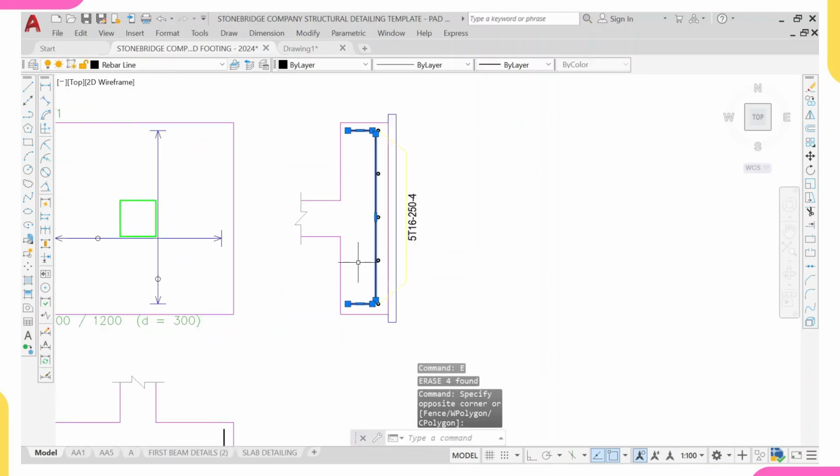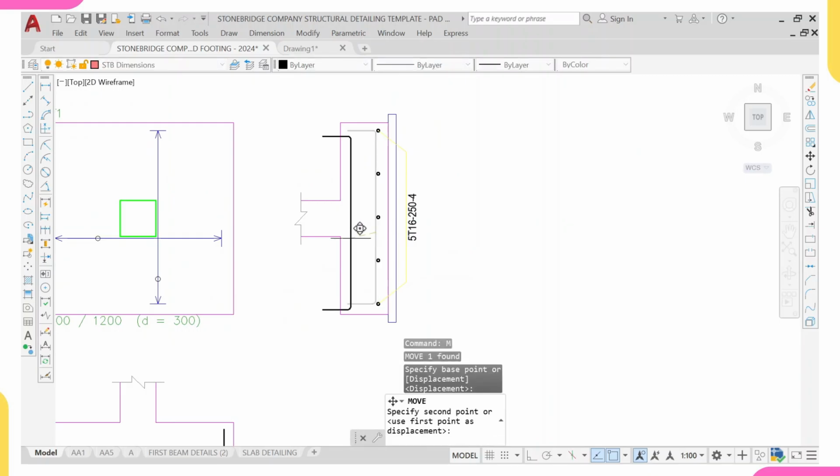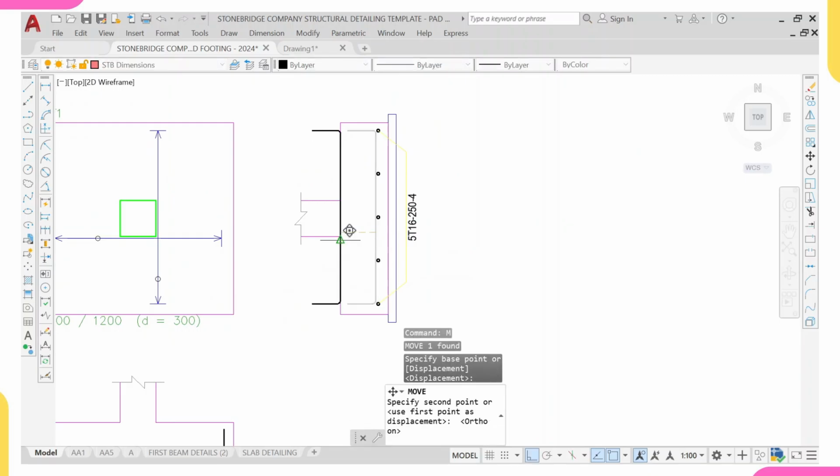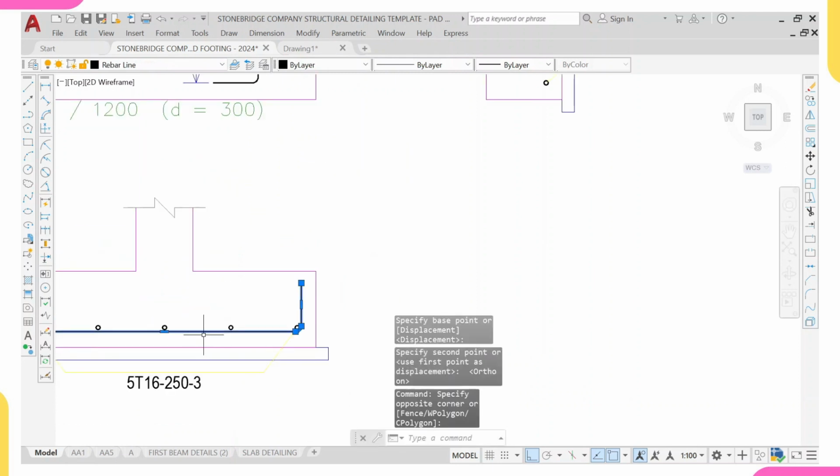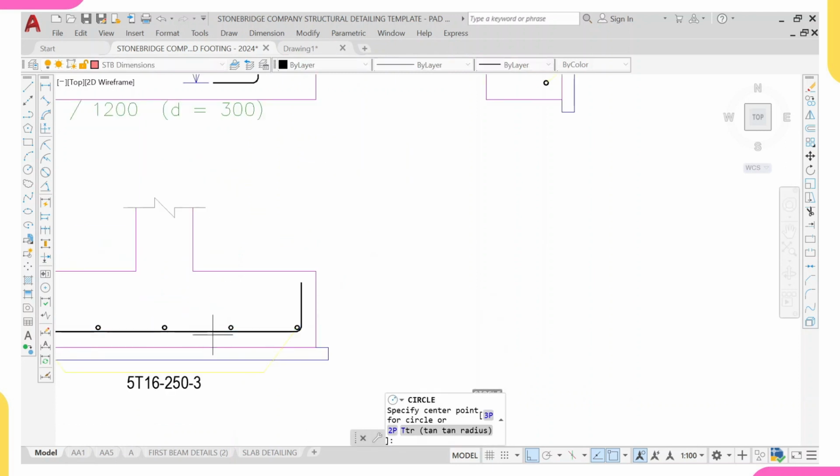Yes, now I'll now be fast. Before I was explaining, but now I'll now be fast. I'll do enter to move. Turn on my auto key again, Control F8. I'll place this thing here. Then I'll copy this one again. I'll do CO, enter. This, which is to copy.